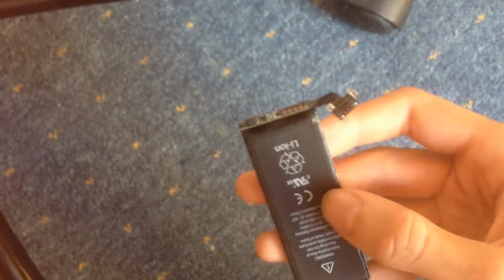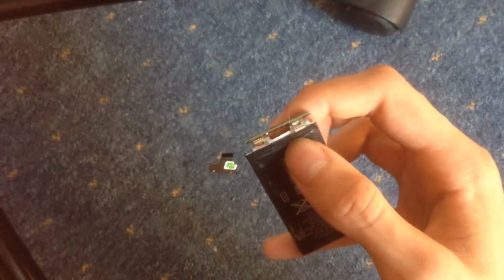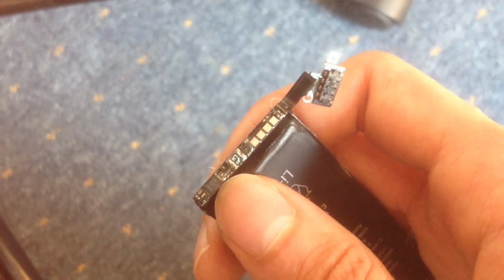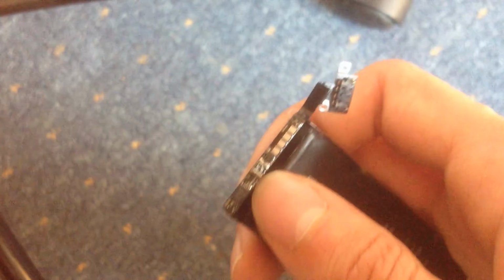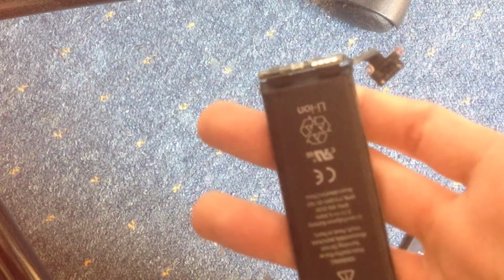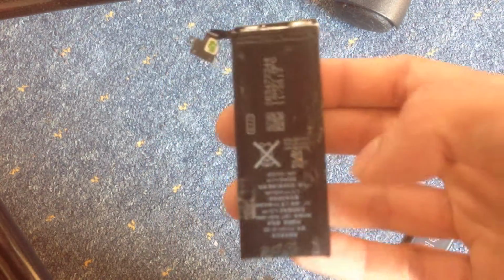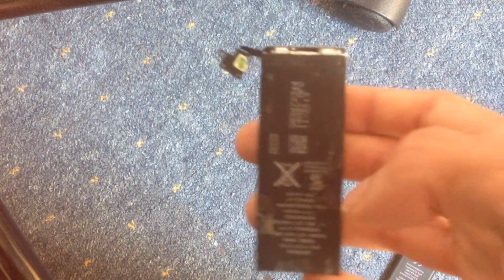There it looks like this, and what we basically need are those two contacts. Because the problem is not the main battery cell, as I just said, the problem actually is this part over here. So I guess it's actually this chip, this IC over here, because it just measures basically the inner resistance of the battery. It measures the current and the voltage to basically get the resistance of the battery, and this is necessary to tell the exact charge.